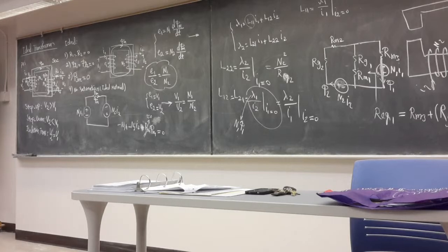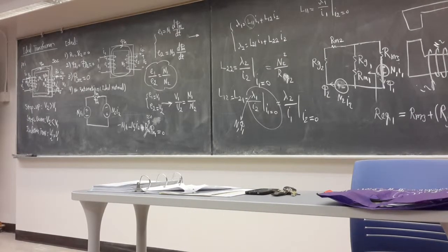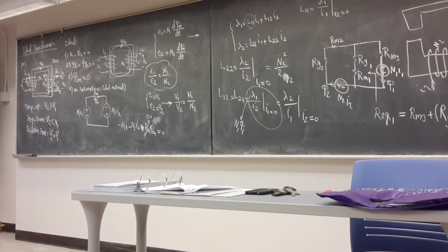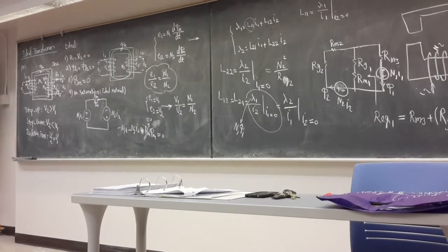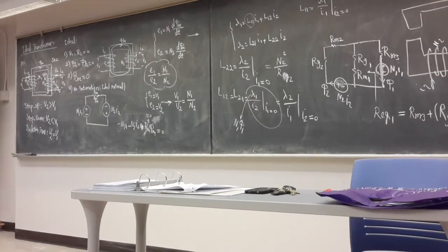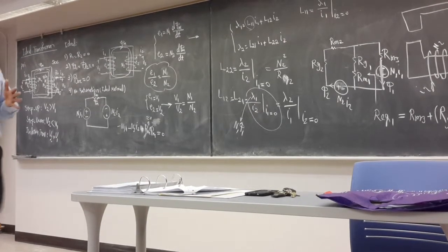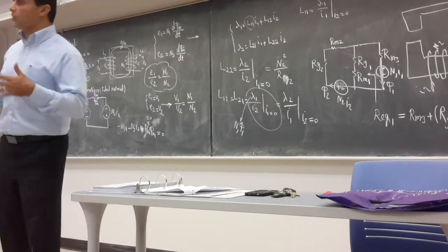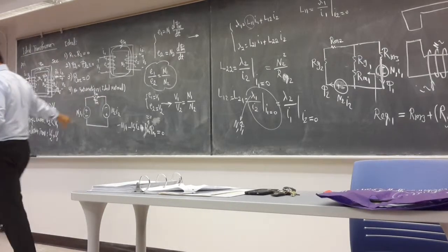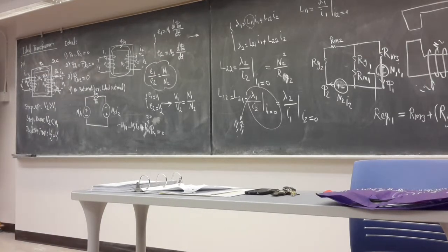Let's say we have a magnetic core material whose permeability is infinity, right? Like a wire. What's the ideal wire? It doesn't have any resistor, right? Do we have an ideal wire? No. Every wire has a resistor. But in mathematics, we can consider an ideal wire, which means there is no resistance, right? Ideal core also means there is no reluctance, right? So what is going to happen?